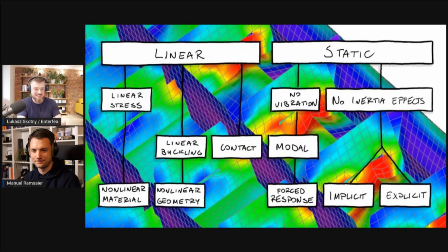So if you have a model and you apply 1 kilonewton of load, and the multiplier is 100, this means that 100 kilonewtons fail your model due to elastic buckling. On the other hand, if you would, in the same model, apply 100 kilonewtons, the multiplier will be 1, but the answer is still the same because it's load times the multiplier.